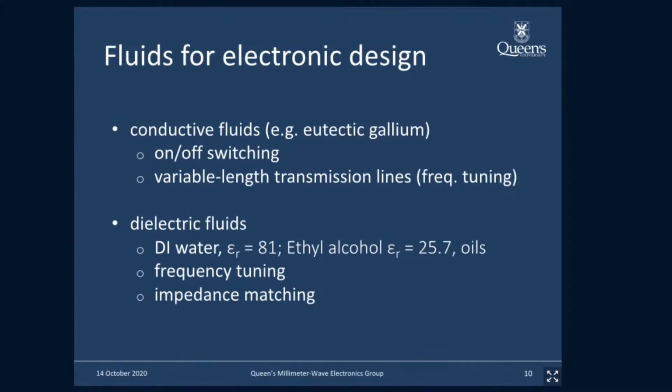And in the area of antennas specifically, tuning of antennas has always been a particularly challenging topic. Why? Well, first of all, if you think about an antenna, it radiates at a frequency that is determined by the geometry, the physical geometry of the structure. So your choices are somewhat limited for tuning it. You can either add metal or remove metal from the antenna, which again, is very difficult to do under normal circumstances.